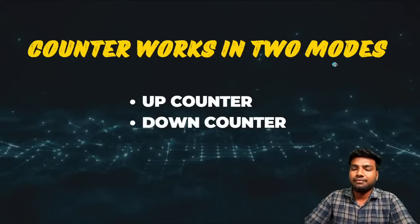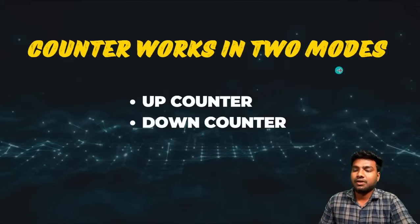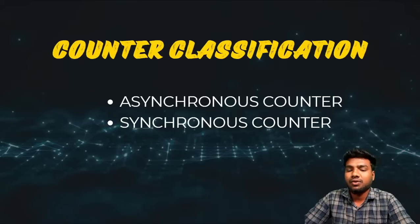We know there are two types of counters, up counter and down counter. Up means it will increment, starting from 0: 0 1 2 3, like that. Down counter means it will start from the limit; if you are using 4 bits, it will start from 15, 14, 13, decrementing. So up means increment, down means decrement. And then the main thing: asynchronous counter and synchronous counter. The name itself says asynchronous.